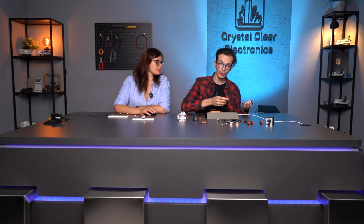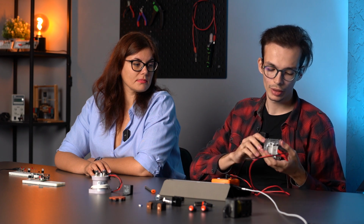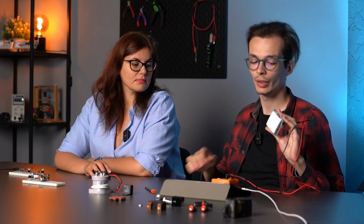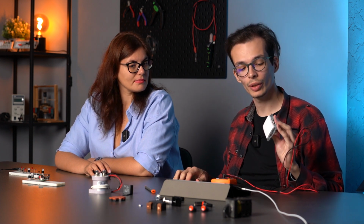The way it works is that if you touch two wires together, the multimeter beeps. Now, I connect the wires of the multimeter to the corresponding outlets of the light switch. And if I switch the light switch, the multimeter beeps. This means that there is electrical contact between the contact and the pole.